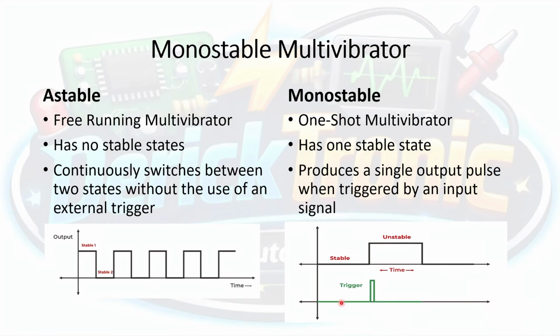So what will happen in our video today, we will be connecting a sort of triggering mechanism to our trigger pin. That will be pin number 2 of our multivibrator. We will be connecting a trigger mechanism there, okay, wherein if I press that mechanism, the output of the monostable multivibrator, the one on pin 3, okay, will go from its stable state, which is most probably the LED is off, to on, the unstable state.